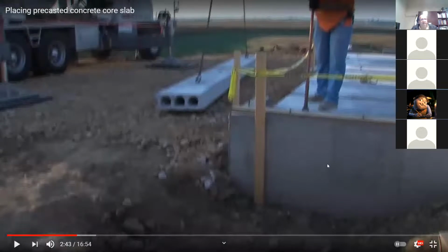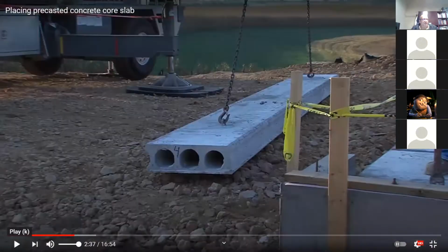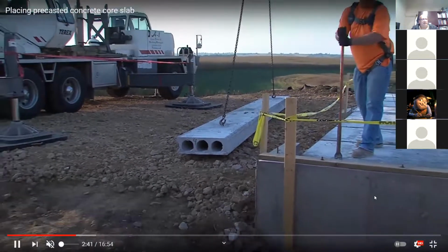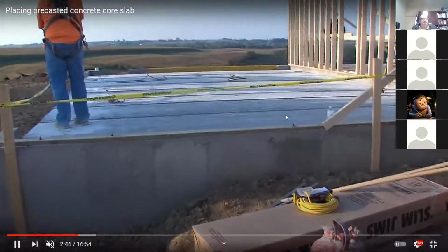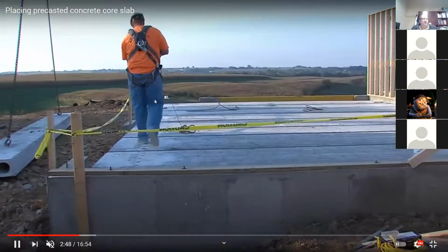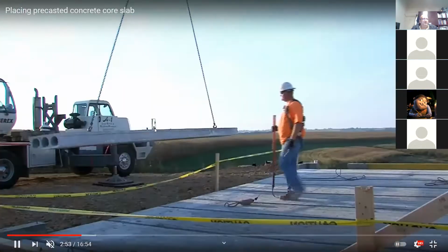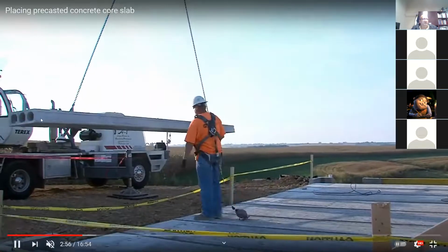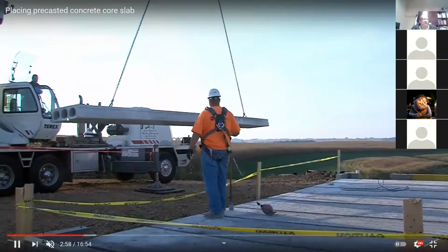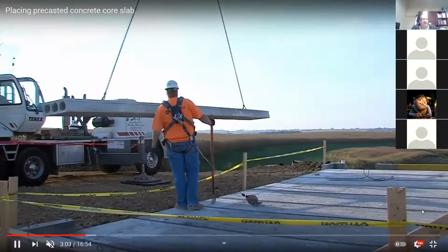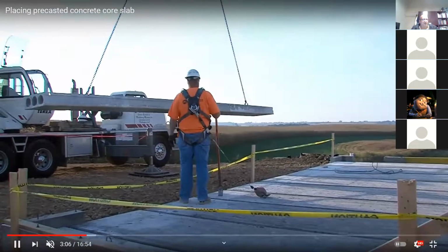You see this wall is below grade, so it's usually going to be used as a retaining wall. Then you come on the top and put all of these blanks, the hollow core. You have a support here, one support here, and this blank spans from here to there. So this is going to be the design for this length. And of course, it's going to be full of these cables. They have cables at the bottom. They put it in place, and after that, they pour some concrete on the top of it